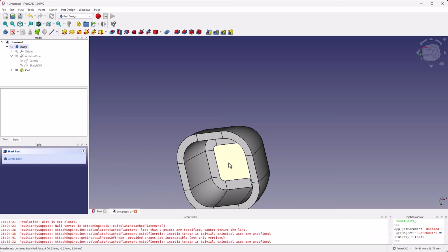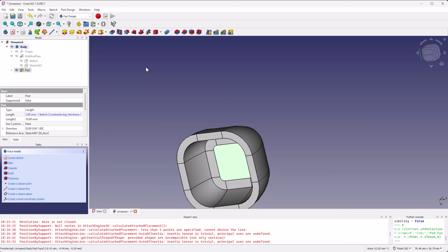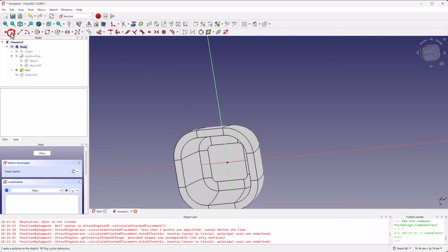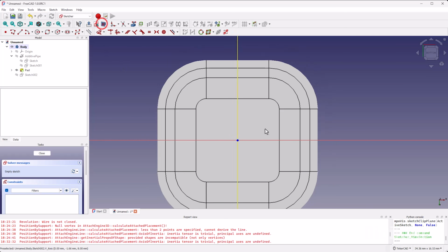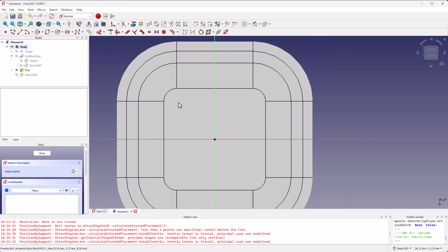Next, we need to define the stem that comes down and connects to the switch. So let's click on the bottom of that new pad we just created. We'll click Sketch, and I'm going to slice the view so we can see what we're working with. I'm going to press G and M to select this polyline tool. I guess M for multi-line. And I'm going to create a quick sketch that I know worked for my purposes, where I'm going to create kind of a stem holder here.